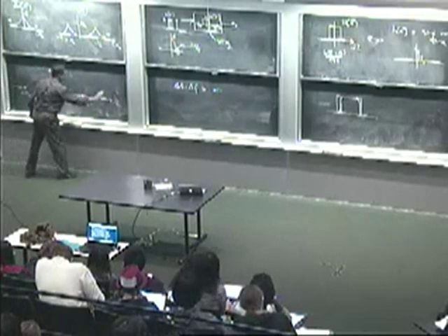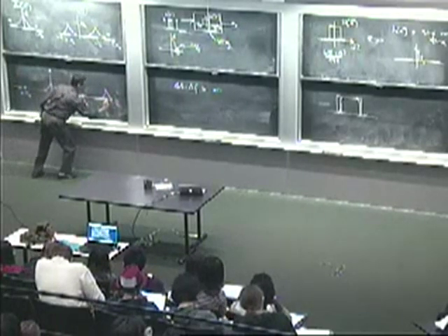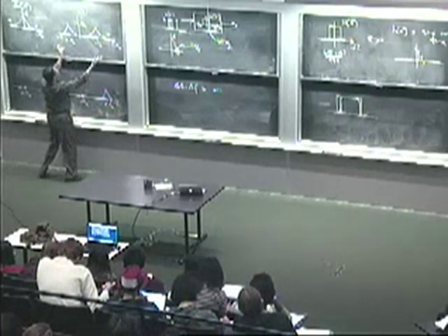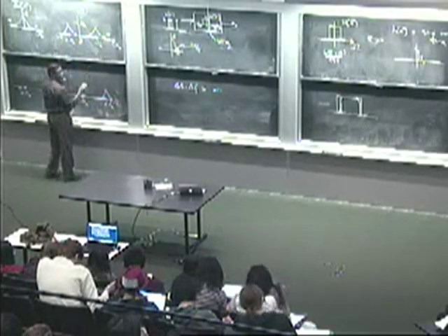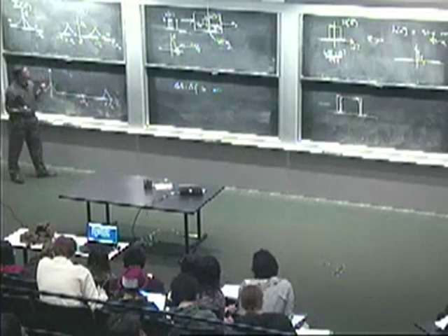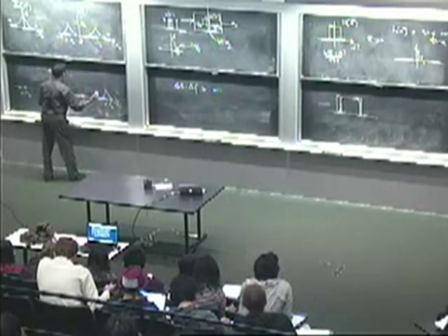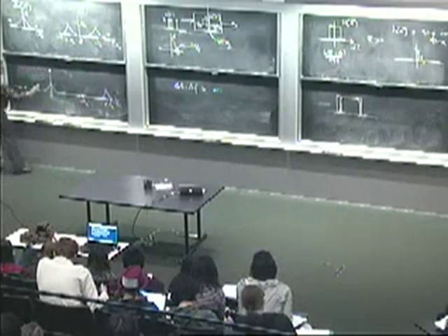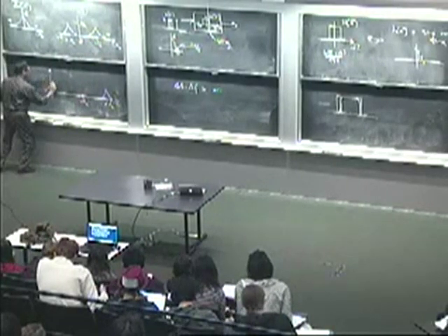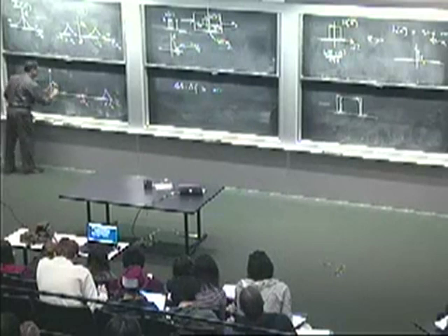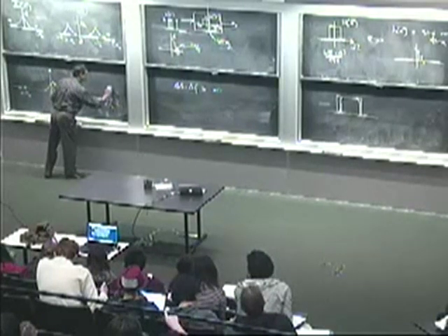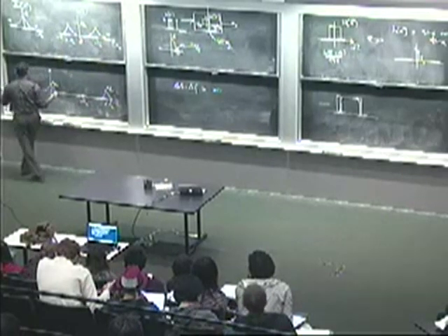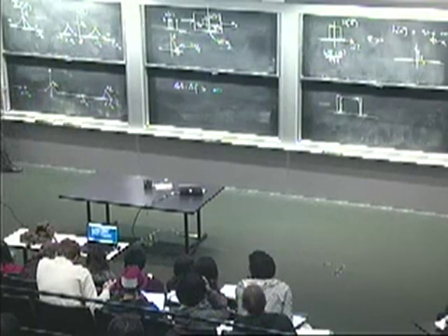It puts a piece here, and it puts a piece here at 2 omega c. Because I've taken this spectrum and I've centered it on omega c, and this is the N over 2 here. Oh, but now it's going to be N over 4, right? Because I divide by 2. And then I take the same spectrum and I center it on minus omega c.